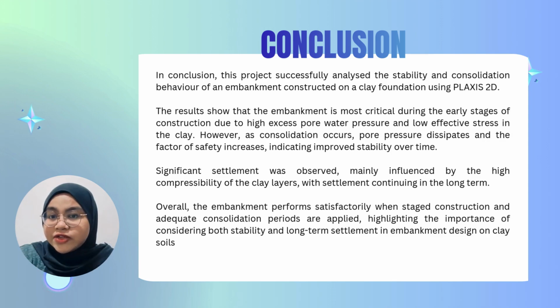The results show that significant settlement was observed, mainly influenced by the high compressibility of the clay layers, with settlement continuing in the long term. Overall, the embankment performed satisfactorily when staged construction and adequate consolidation periods are applied, highlighting the importance of considering both stability and long-term settlement in embankment design on clay soils.